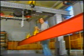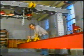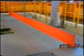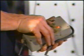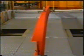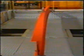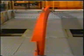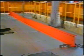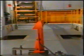The second beam is 7 metres long and is much more slender. The load is applied as in the previous test. Observe the response, shown again in an accelerated manner. It can be seen that significant lateral deformation and twisting occur, in addition to the in-plane bending displacement. This is known as lateral torsional instability.